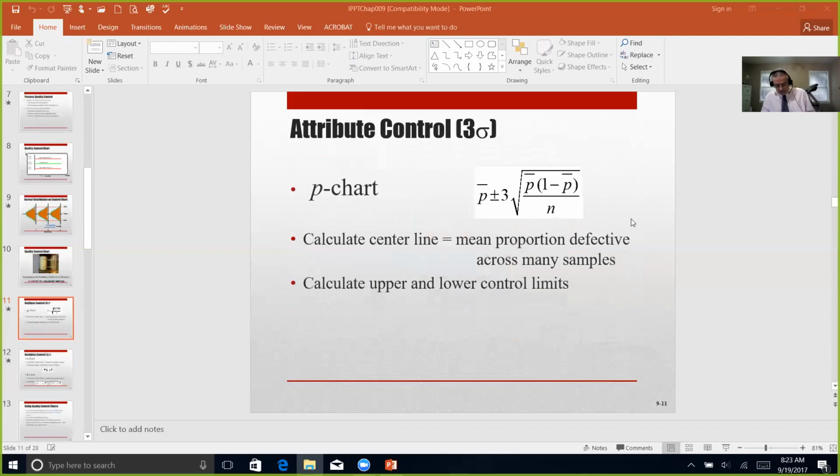So over on page 195, 196, we get into the attributes of control, where we're using the P chart. The P value is computed for each sample, then averaged over all samples to yield a P hat, and the P hat is used as the center line since it represents the best available true average measurement, and you see that particular formula again over on page 195, where you have an upper and lower control limit.